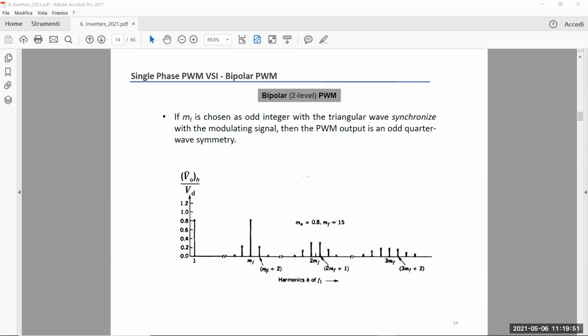Okay, we computed the maximum ripple for the unipolar and the bipolar pulse width modulator in that situation. And we compared what happens in these two situations. We learned that the output ripple for the current flowing in the inductor for the unipolar one is, say, half that you can have in the bipolar one, having the same filtering at the output, because this happens as a result of this spectrum contribution at the output.